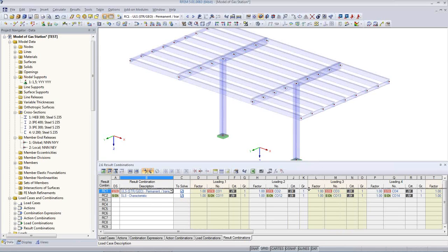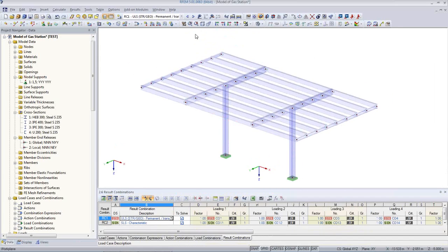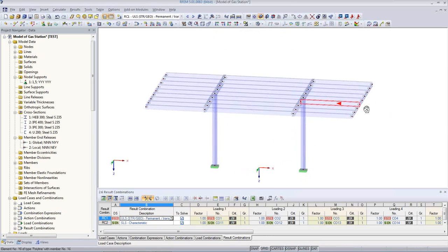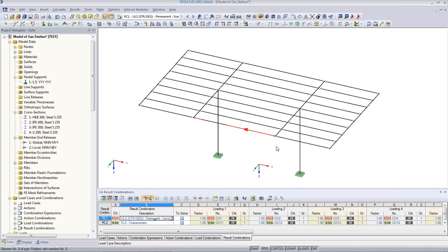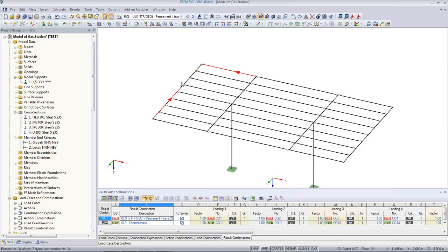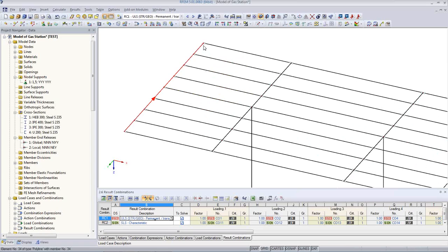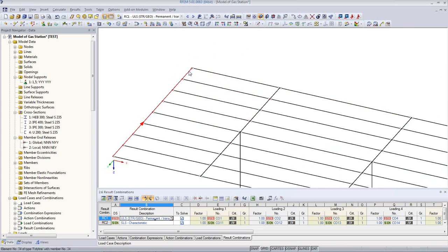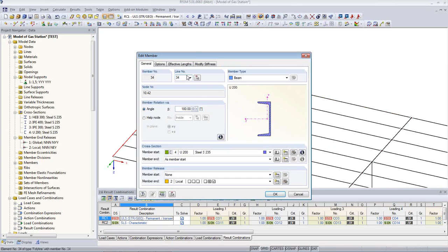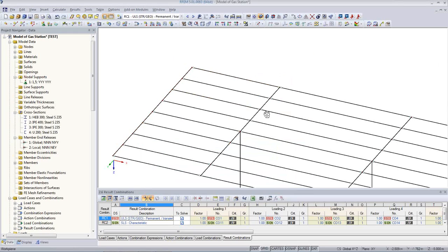Okay, next we'll have to enter some loads, and I'll have to speed up a little bit so we get ready within the right time. I'll change the view to the wireframe view, and while I do this, I noticed I have made a small mistake. I see there is also a release here. To avoid any complications, I'll just set this to none and change it.